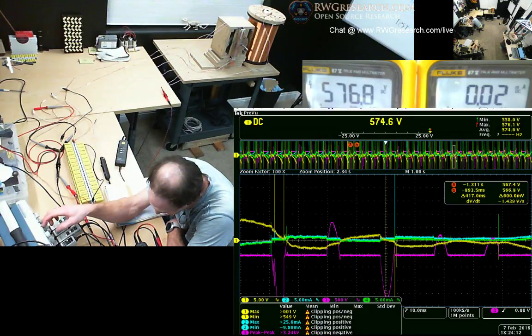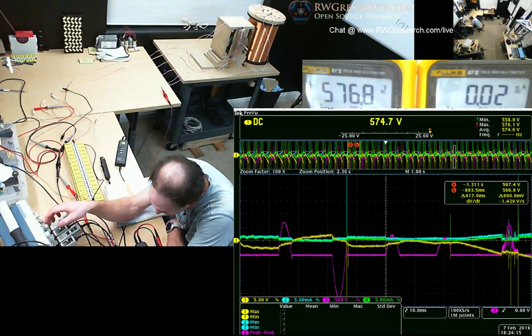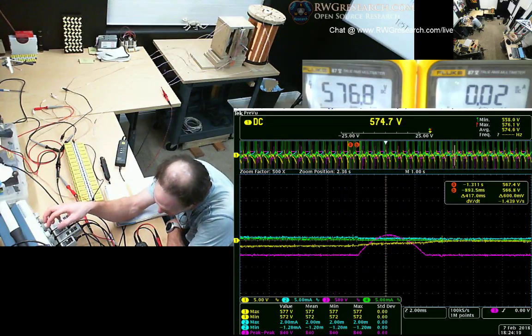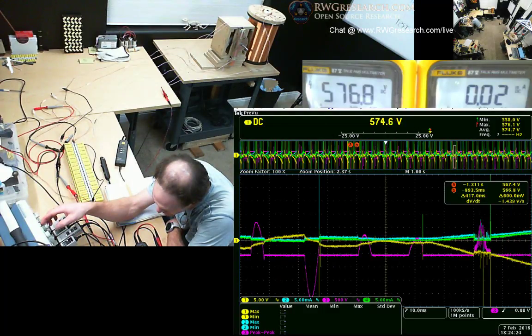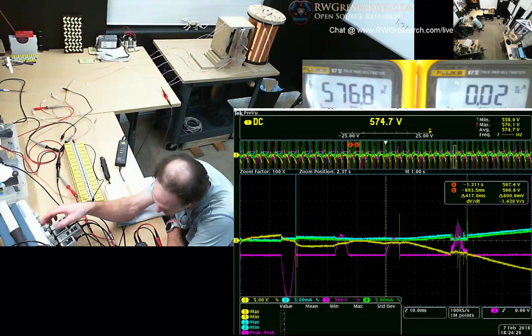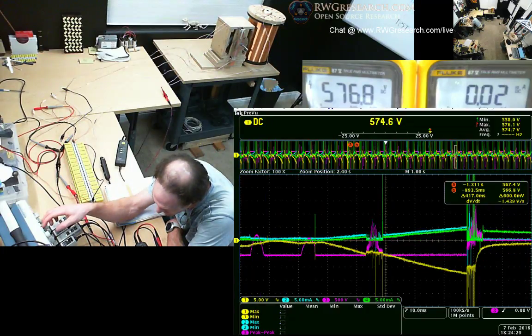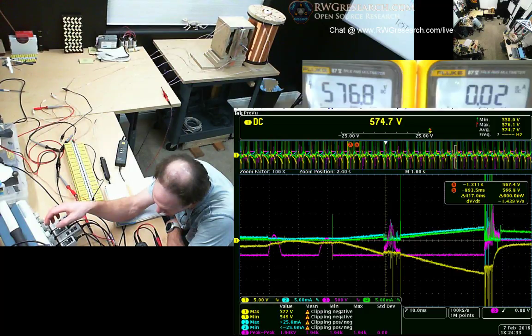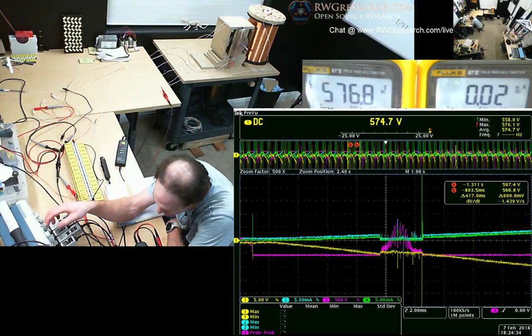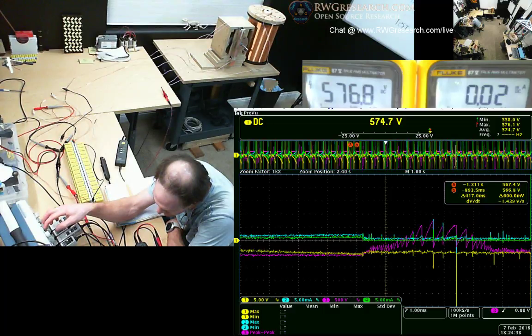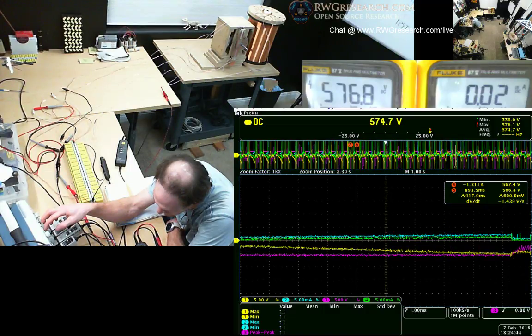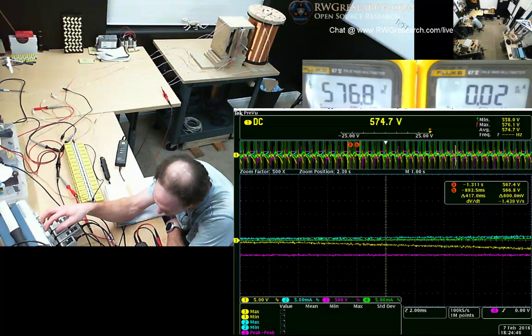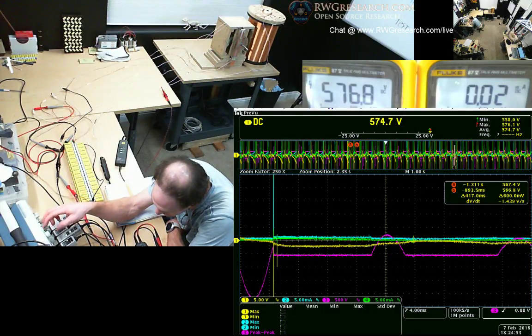I guess what I need to do is cut the other side similarly, but make it shorter. Because see, this last one's shorter than the other ones. We cut them 6 degrees. I should have stuck with like 4 degrees, so that the cycle would be shorter and then it would arc back over at that cycle. You know what I mean? You could solder a little piece of foil in there. I think if I solder anything, it might throw some stuff off, but I can try it. This commutator is going to be toast eventually because of the arc over it's had a few times.